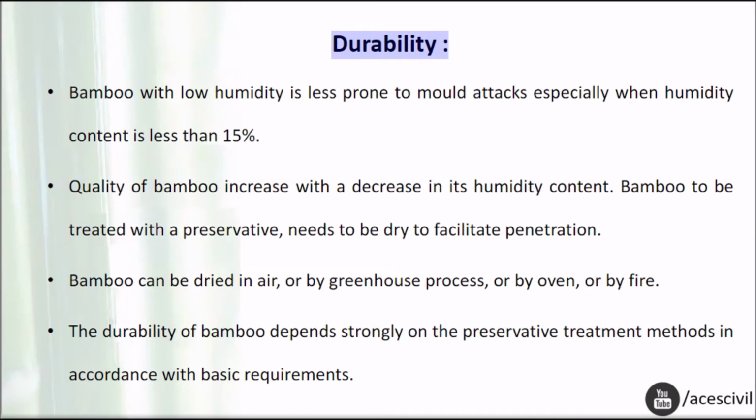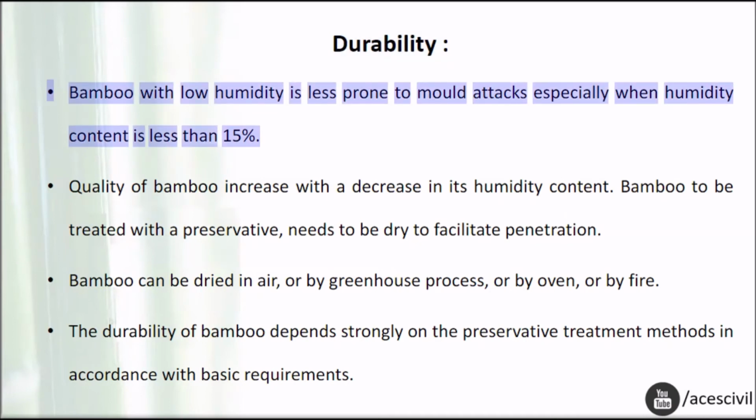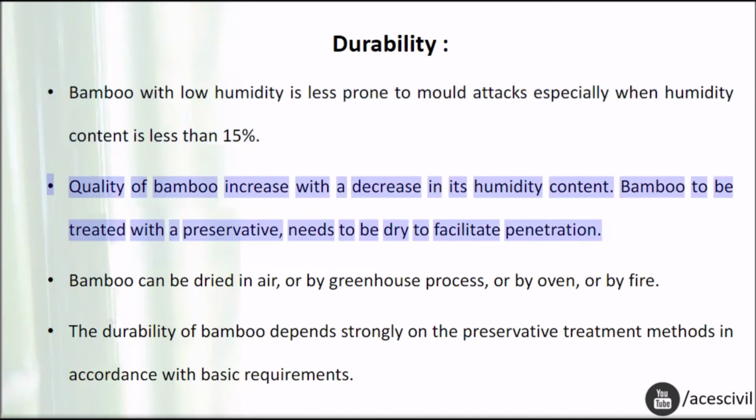Durability. Bamboo with low humidity is less prone to mold attacks, especially when humidity content is less than 15%. Quality of bamboo increases with a decrease in its humidity content. Bamboo to be treated with a preservative needs to be dry to facilitate penetration.